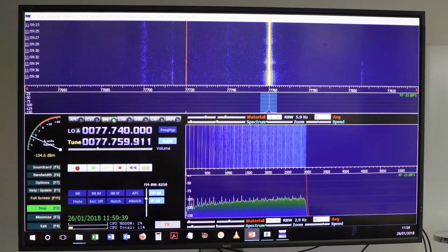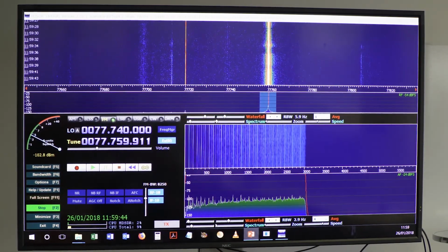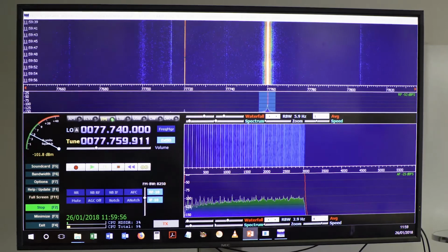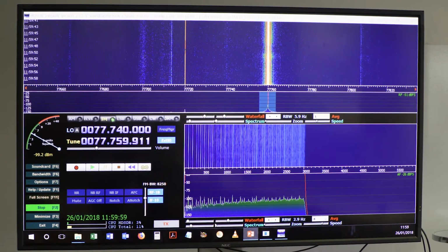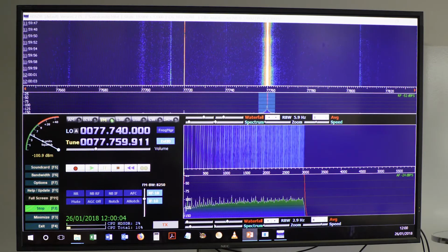For this antenna length, it seems that the maximum is there. Okay? It's maybe a little bit less optimized than if I would retune the tuner of the antenna. It's already a little bit better, so even fine-tuning a little bit more, it's better. Because there is no miracle. The more you approach the quarter wave, the better it is.